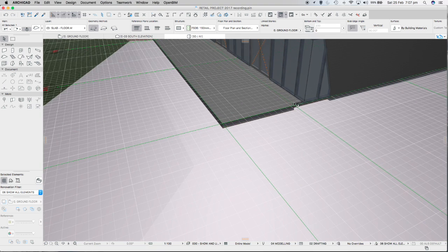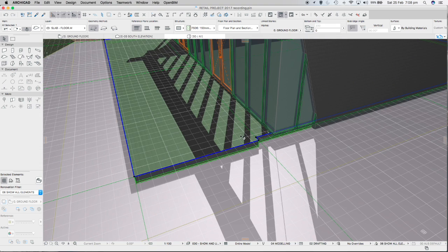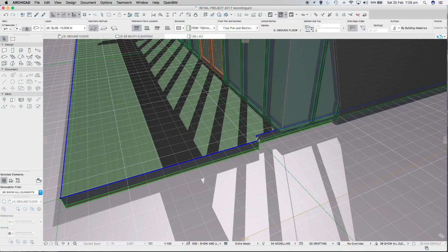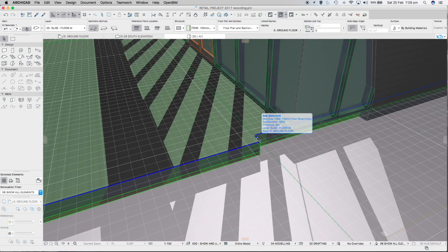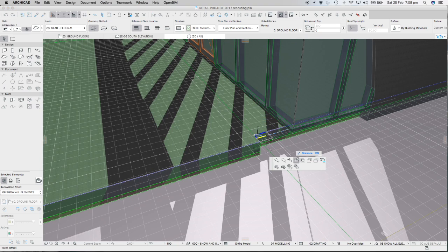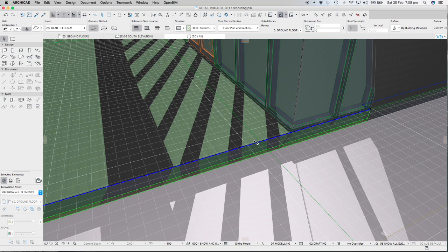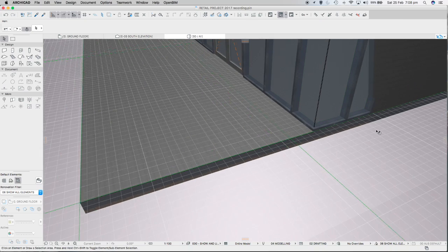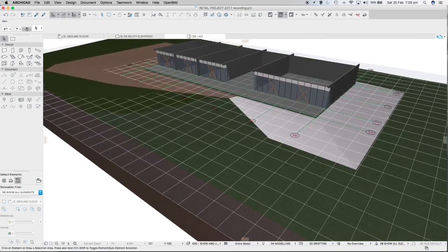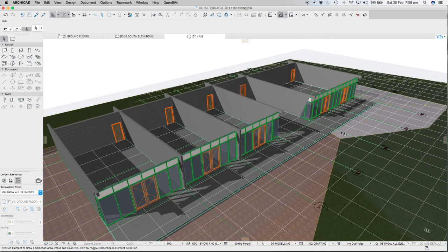And you'll see again, if you haven't picked up what I'm doing, you'll see again a bit clearer on this end with that slab selected. I'll select that slab. This is the edge that we want to move, so I'm clicking very carefully on this edge. And then if you use this pet tool, you can offset that edge and slide it along. It's always good to try and find a point that you know of. It doesn't have to be in the same plane. So you can see I'm coming down to the bottom of this concrete tilt-up, and when I click on there, that's stretched it along until it meets that concrete tilt-up at that point there. So there's the floor slab done. I'll stop the video at that point.